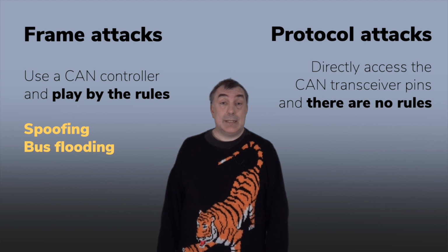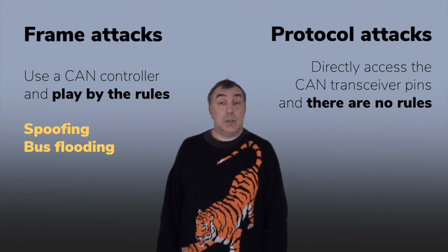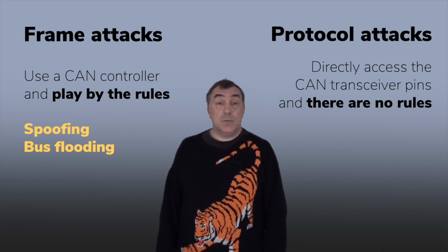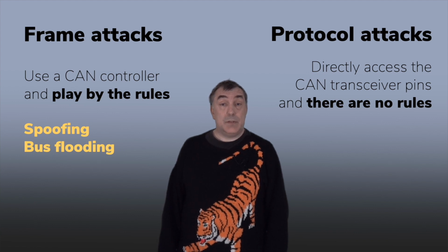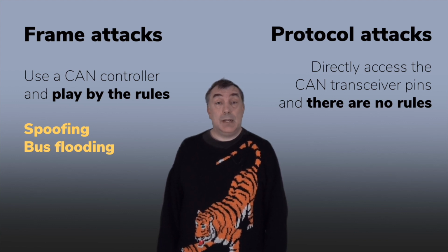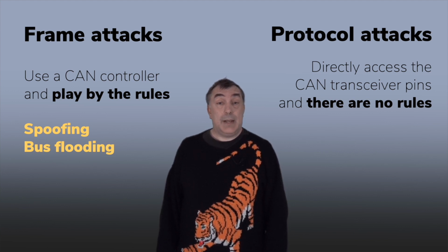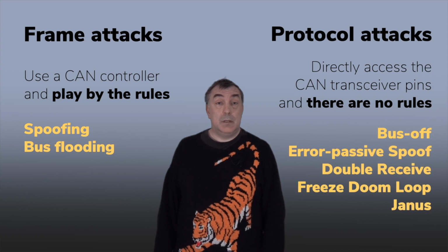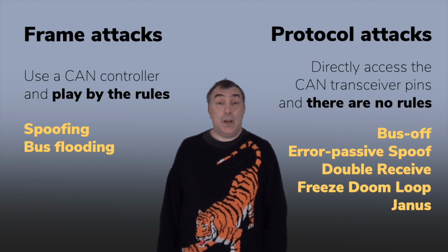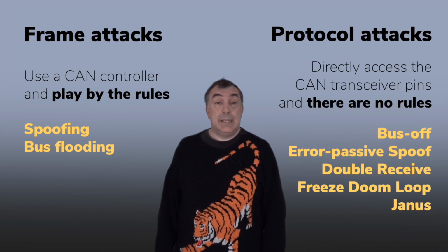CAN protocol attacks are different. They're attacks on the CAN protocol itself. They work by software directly accessing a CAN transceiver's pins and can drive an arbitrary signal onto the bus. This means there are no rules. The software can do anything to drive the behavior of other CAN controllers on the bus. This talk is going to demonstrate 5 different CAN protocol attacks. These attacks are especially important because they can be combined together to achieve higher level attacks.